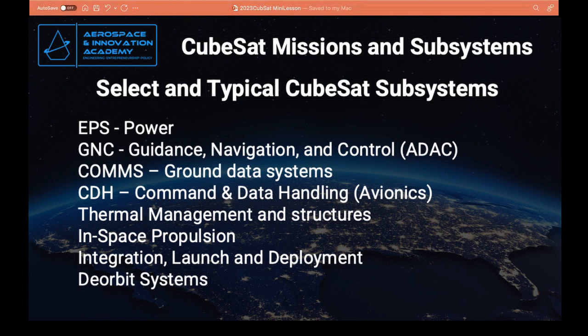We can use coatings to help protect some of our electronics, and definitely shielding against radiation. As I mentioned earlier with the avionics, we can use aluminum and titanium alloys. One of our students was interested in polyethylene as a potential barrier for radiation, because space has a lot of particles and EM radiation.